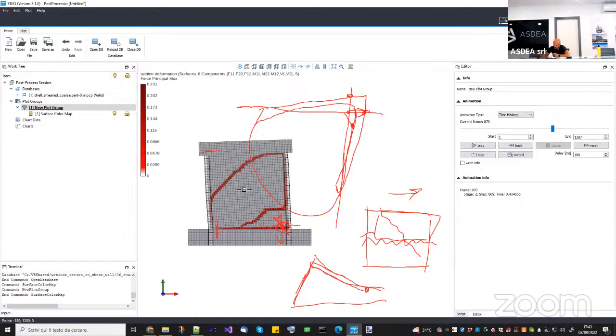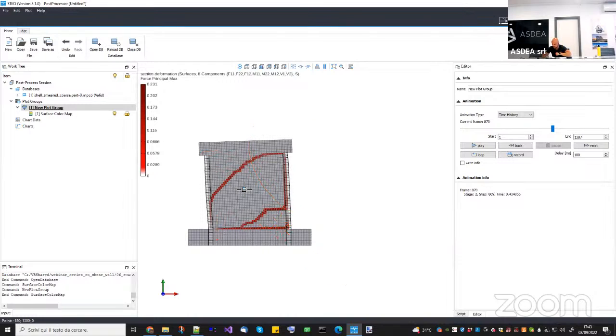Now, on the opposite, what I see from either the truss model or the fixed models in general is that it is the opposite, basically. That's why I say it is on the upper bound. If I imagine a representative element from the beam truss model, something like this, and imagine this one is subjected to uniaxial tension in the vertical direction, what I will see is that this element will deform like this.